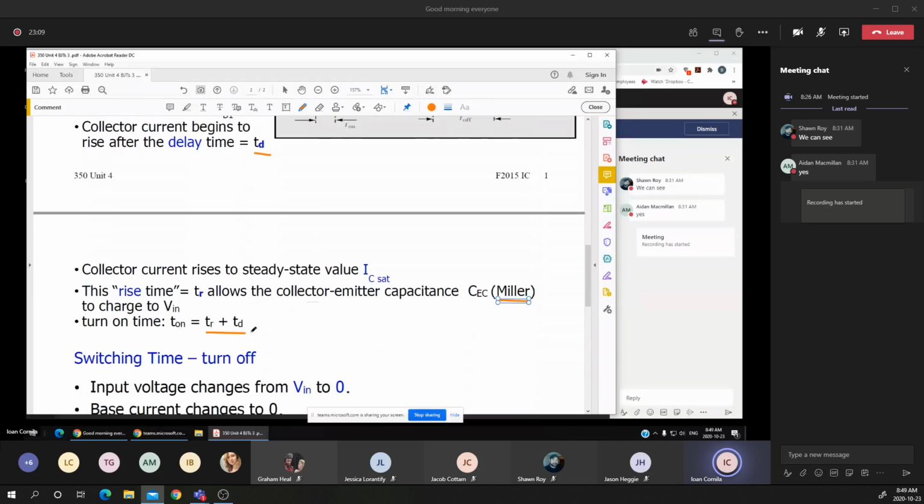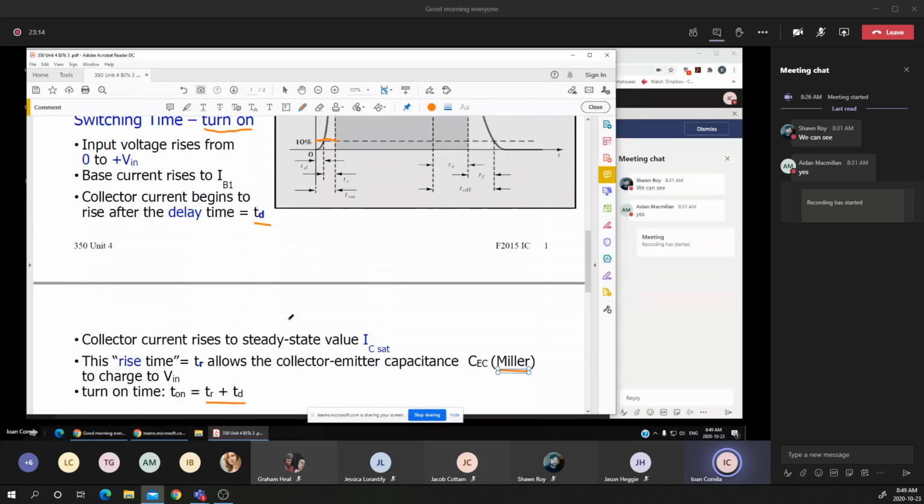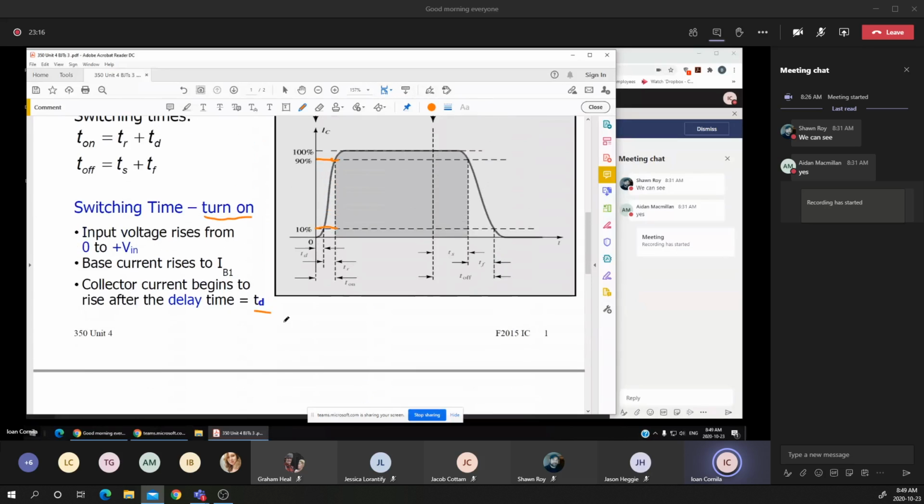The two values of the TR, TD given in the specs mean that we can determine the shape of the waveform that is expected when the transistor is turned on. Once it is turned on and reaching the maximum voltage, it will stay on with a maximum value for the current, but the same observation occurs when the transistor is turned off.